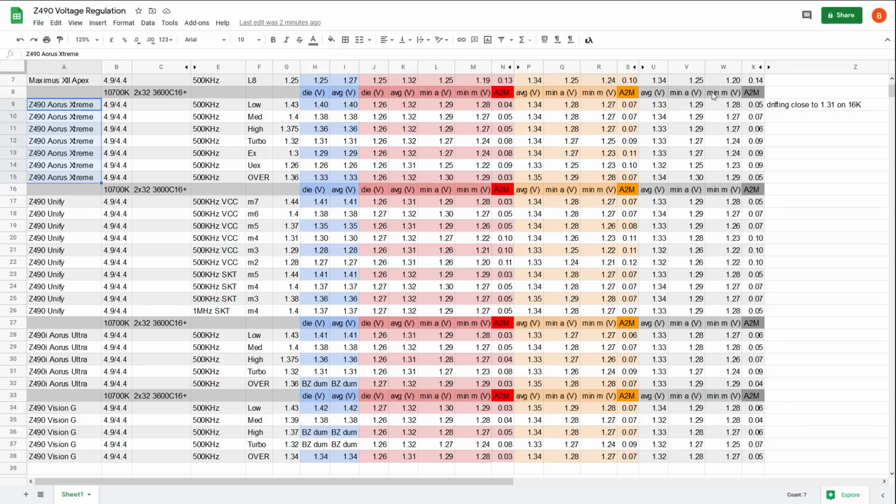And yeah, they perform the same. So I was kind of hoping that the ITX would maybe do a bit better, because sometimes that happens, where ITX boards perform better because of only having SMD capacitors, and also because the power plane usually ends up being shorter. ITX boards can sometimes overperform in voltage regulation, even if their VRM ends up running hot, because they're ITX and there's no space for large enough heat sinks.